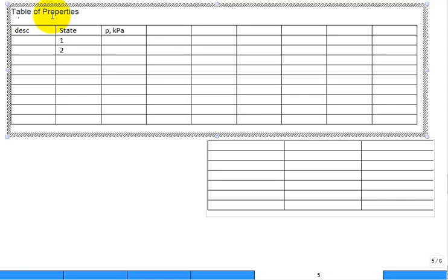Basically, get them all into kilopascal and put them all in one column. And then the temperatures, we could put Kelvin, but it's common to use C in our tables for steam. It's all in degrees C. And then we don't use this column that often, but I like to put it: quality. Same for the specific volume, and the specific volume is meter cubed per kilogram. And then our enthalpy column, kilojoules per kilogram. And then our entropy column, kilojoules per kilogram Kelvin. Looks like I got an extra column, but that's okay.